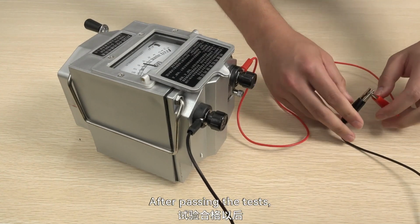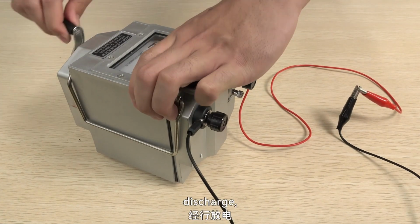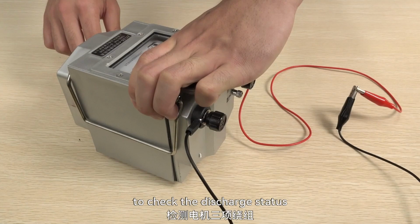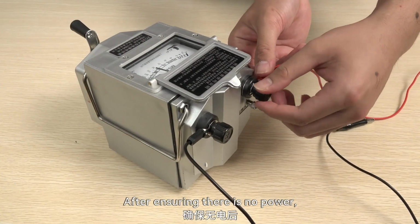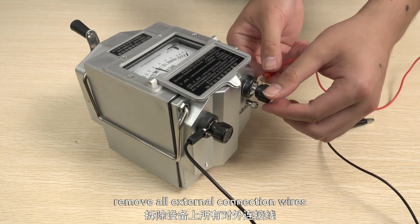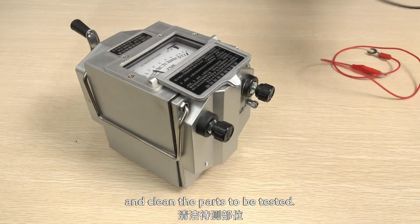After passing the tests, first turn off the power of the equipment being tested, discharge, and then use a voltage tester to check the discharge status of the motor's three-phase windings. After ensuring there is no power, remove all external connection wires and their connections from the equipment and clean the parts to be tested.